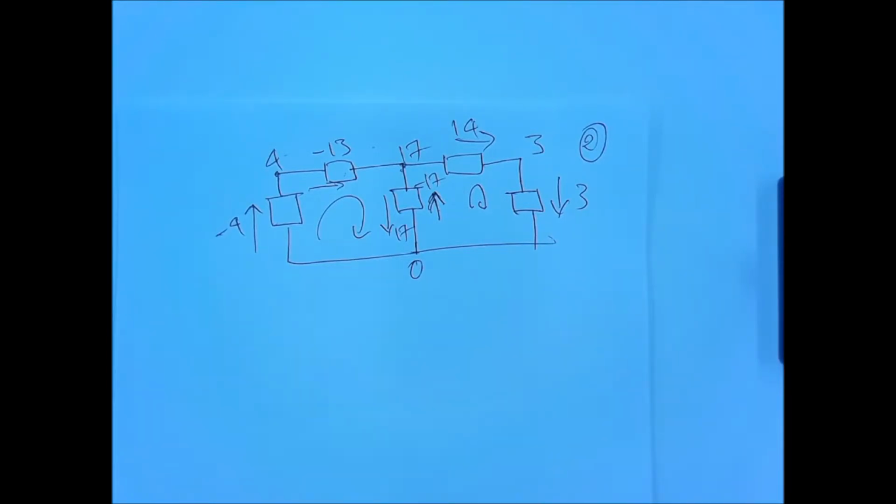So the potential drop between these 2 points is moving an electron or a point charge in this electric field from this point to this point. Let's say this is 0. The potential at that point would be the work it takes you to move that charge from here to here. But on the other hand, I can also take it from here to here. What KVL says is, no matter how you go, you should be able to do the same amount of work and get there.